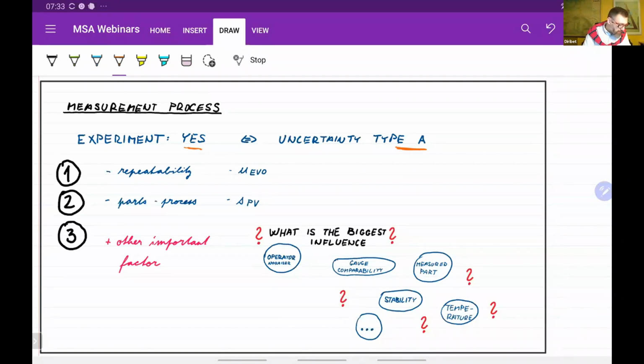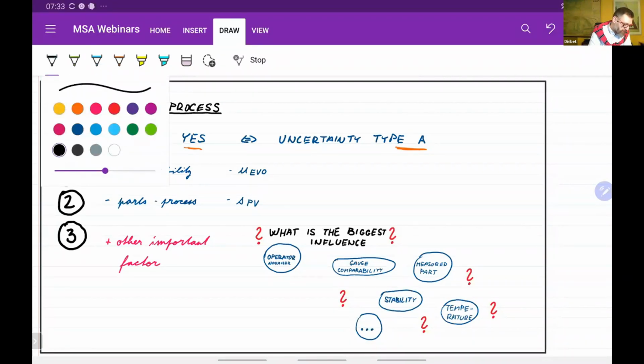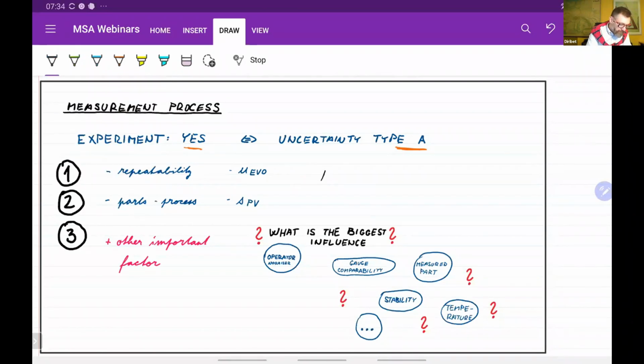It always includes the repeatability in the first place, and we already had a repeatability. The standard deviation is denoted by U. The repeatability was for EV, that's for equipment variation. And we had a reference in the measurement system. Now we get rid of this R and substitute it with an O for an object. And that's slightly different thing.